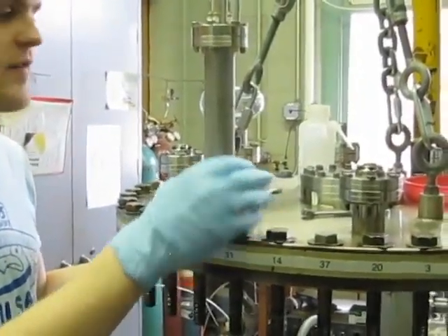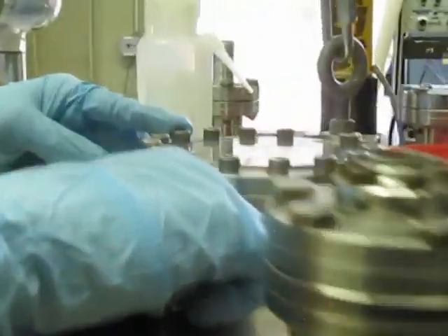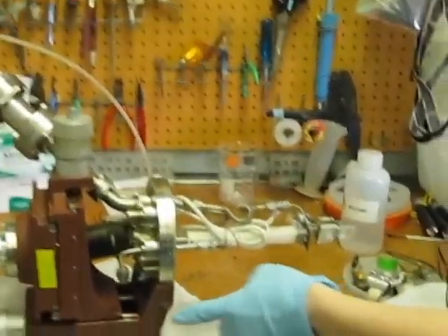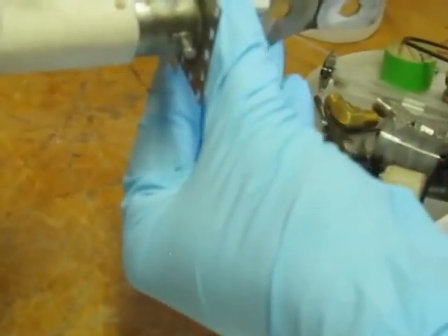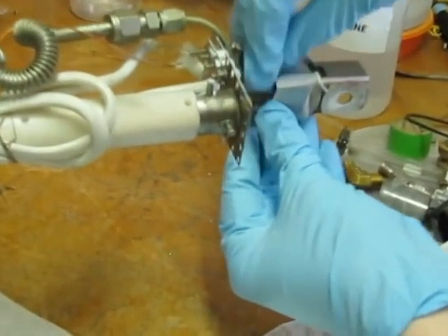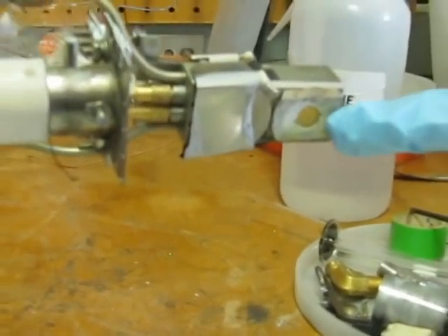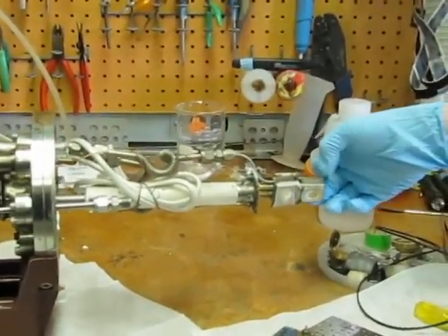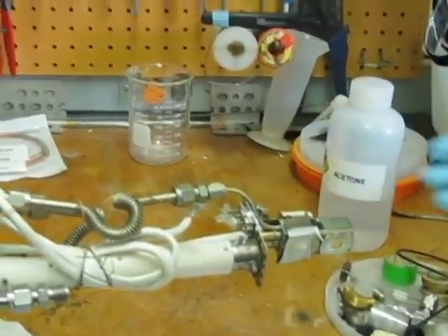This is the lid of the main chamber. Here on the center flange, we will mount the QCM diagnostic, which you can see here. You'll notice that the QCM, or quartz crystal microbalance, has two crystals. One is covered. This way we can measure the background signal as well as the crystal that is measuring sputtering yield in situ. This allows us to filter out temperature dependence and other noise.